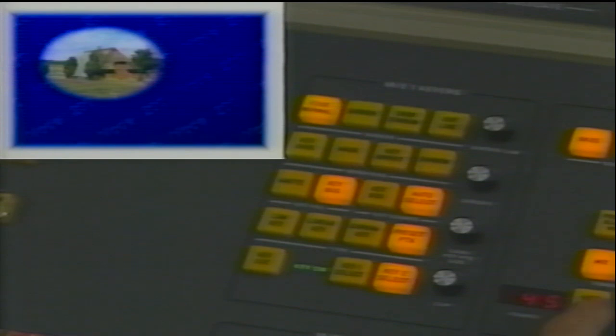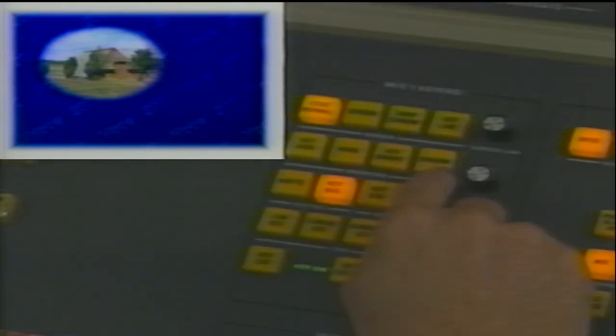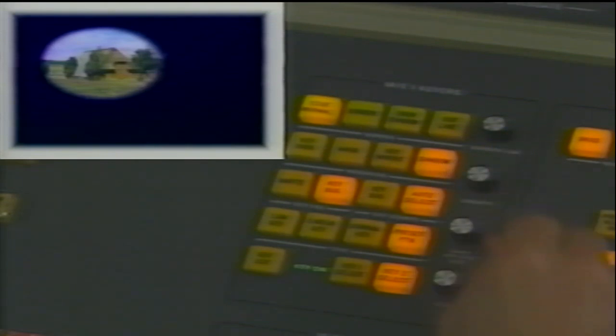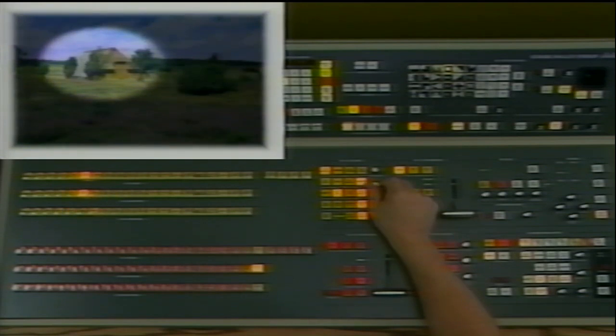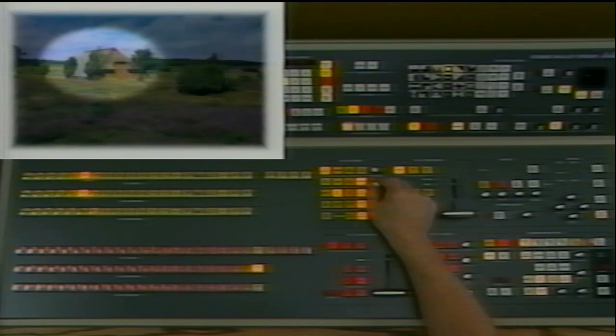In preset pattern, the shadow control has yet another mode of operation. When activated, shadow attenuates or dims the entire field outside the preset pattern. When we bring up the same background video which is filling the preset area, we create a spotlight effect. We can now adjust the density control and modify the spotlight effect being created. Key invert and mask have no effect in preset pattern mode.